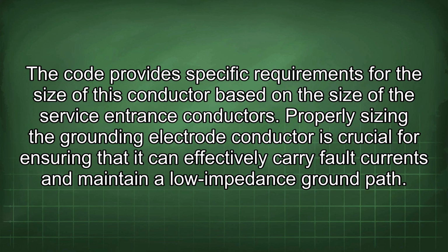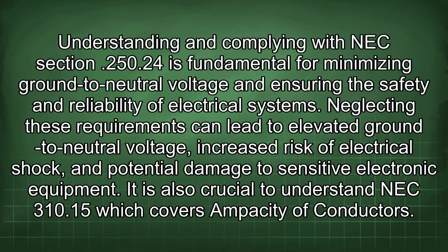Understanding and complying with NEC section 250.24 is fundamental for minimizing ground to neutral voltage and ensuring the safety and reliability of electrical systems. Neglecting these requirements can lead to elevated ground to neutral voltage, increased risk of electrical shock, and potential damage to sensitive electronic equipment. It is also crucial to understand NEC 310.15, which covers ampacity of conductors.